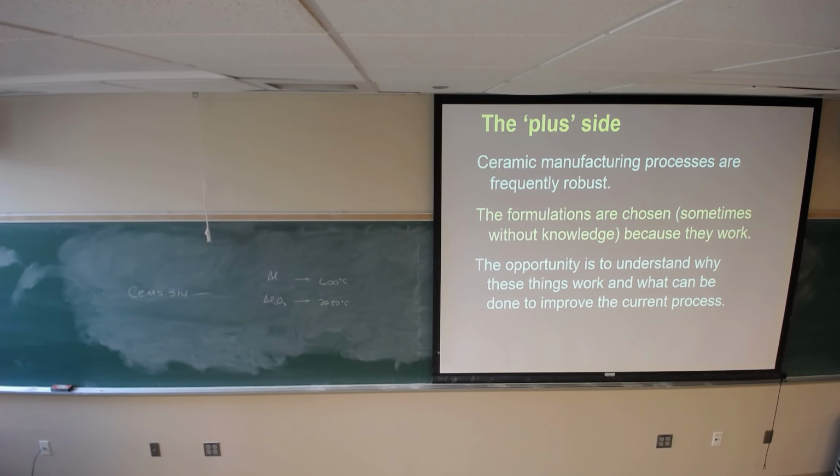That sounds a little strange. What they're doing is they work in the sweet spot. They work in an area where small variations in packing efficiency or mixing do not result in a significant difference in shrinkage. The consequence of that is that they can actually manufacture parts and put them in a box and send them out. It's in many respects a self-correcting idea.